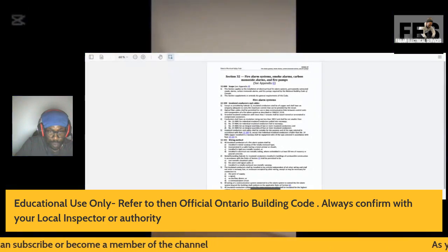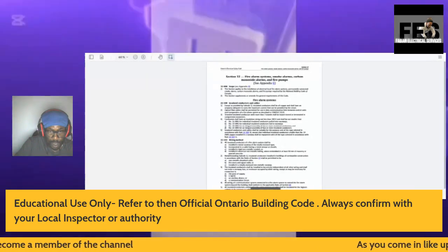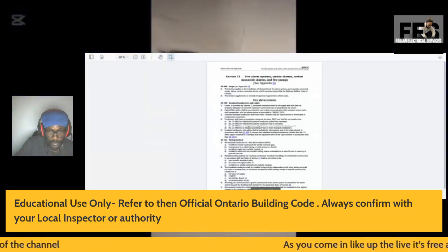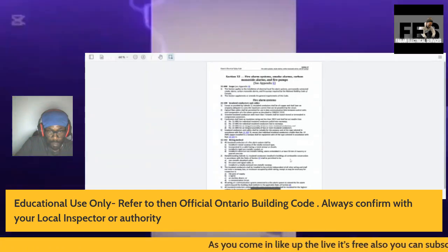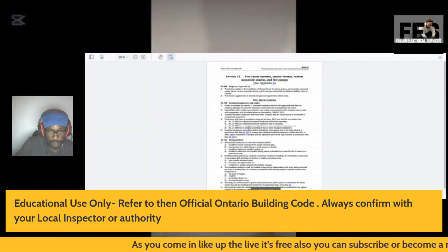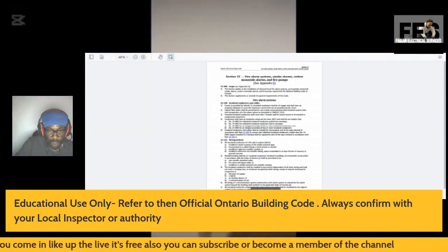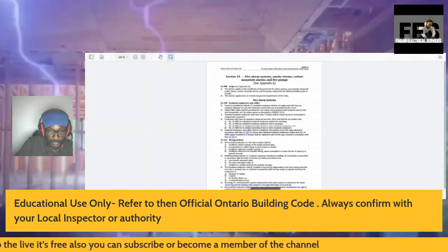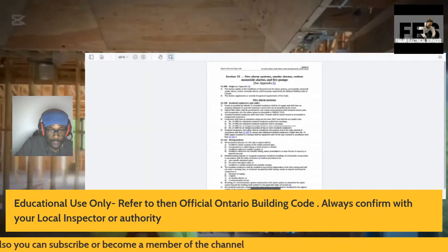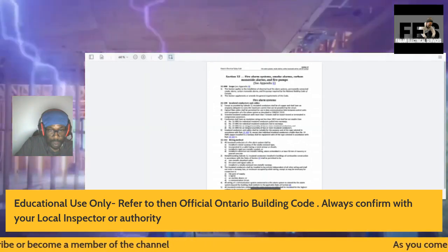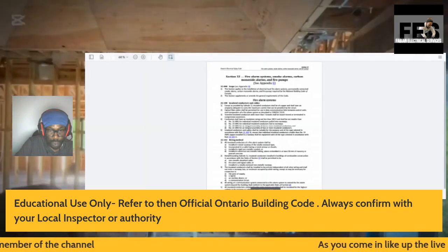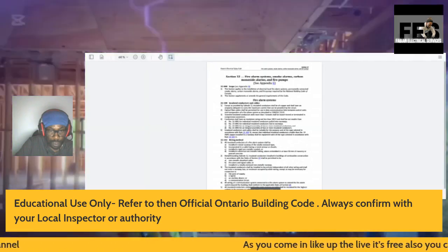Notwithstanding Subrule 1, insulated conductors installed in buildings of combustible construction in accordance with the rules of Section 12 shall be permitted to be non-metallic sheathed cable, fire alarm and signal cable, or installed in a totally enclosed non-metallic raceway.